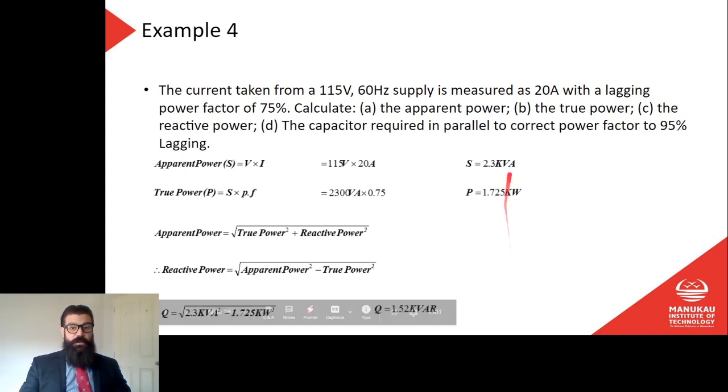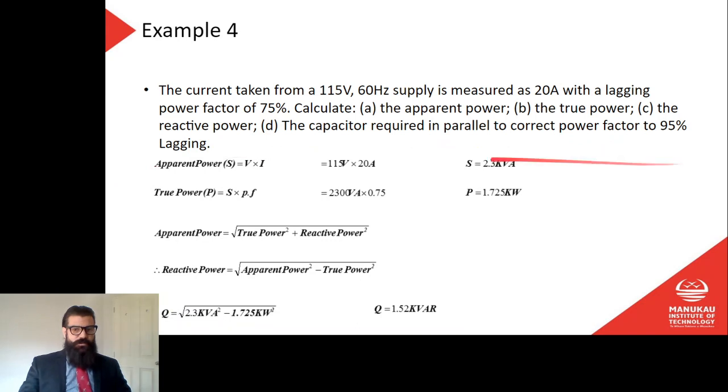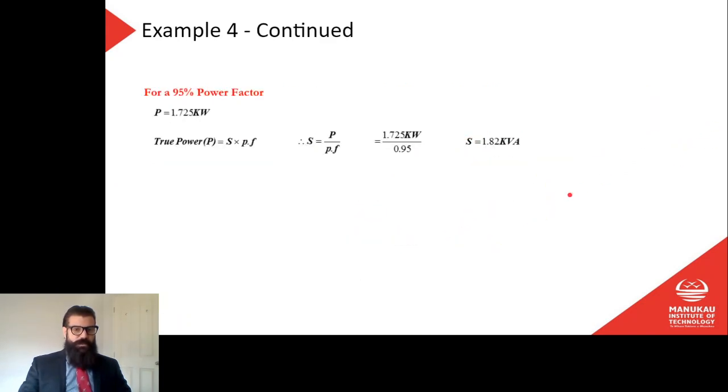So now I've got apparent power, the true power, and the reactive power. Now I just need to work out the capacitor required to bring that power factor from 75% to 95%. Let's have a look.